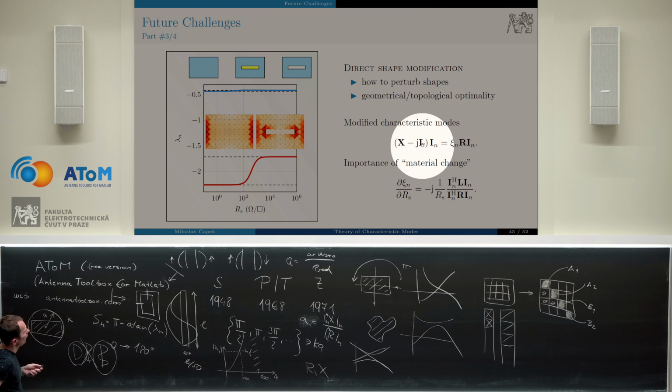If you modify the eigenvalue problem slightly so that on the left-hand side, you also incorporate the ohmic-loss matrix. And why is this done here? Because I'm saying that the future slot cut in the middle is filled with some material having ohmic losses, and these ohmic losses are parameterized by RS.